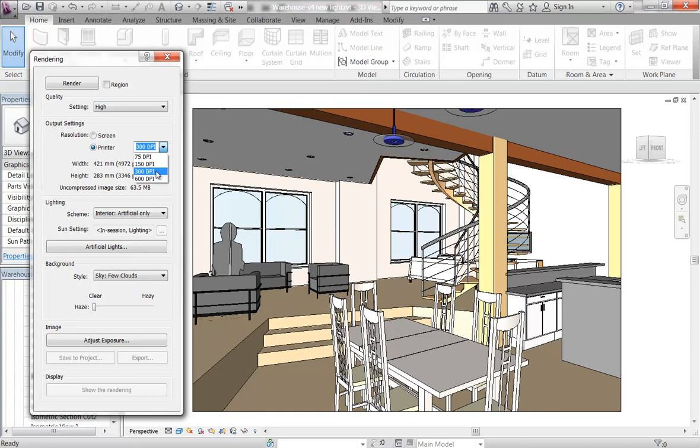If you can, that's the best, because these plotters will easily print that, and you'll notice the difference. But if you have to, 150, even though it sounds like it's a lot less, because it's a quarter the pixels, you won't notice that much of a difference, especially on a larger image. On these printers, you'll get away with it most of the time, and you can render it in a much more practical time period. So think about that, and you can see that's still quite a lot of pixels. That will take at least an hour or two to render on the highest quality. So that's still something to plan for.